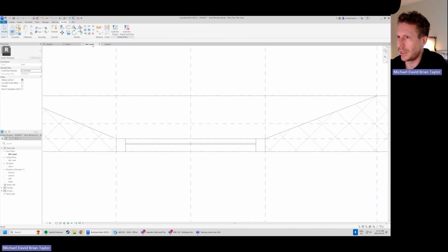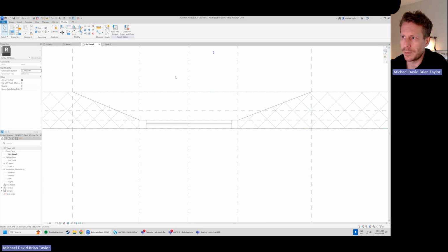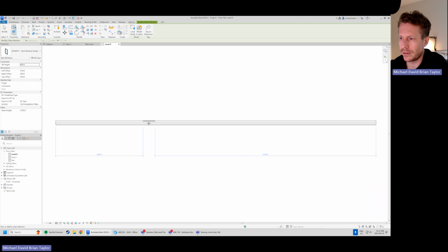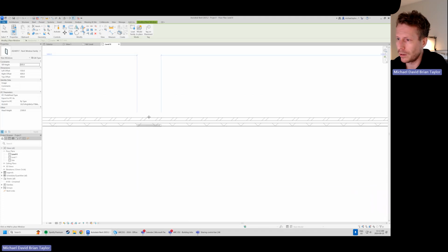family. And then we're actually going to load. Let's make sure we save this. So make sure you save as much as you can, a little save icon. So save somewhere smart, and then load into project. You'll see over here, if we've got nothing selected, we can load this into a project, and let's load it into here. So we've got it loaded now into our project. Revit has said, okay, cool, you must want me to load it into here.